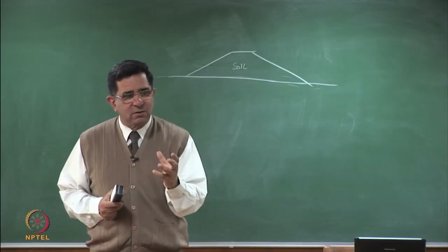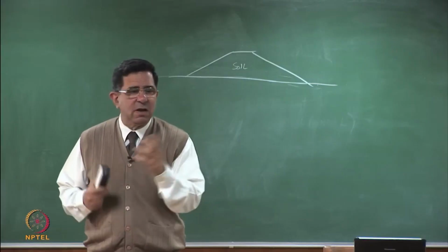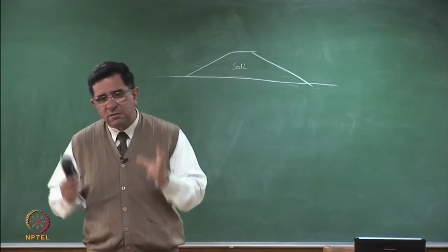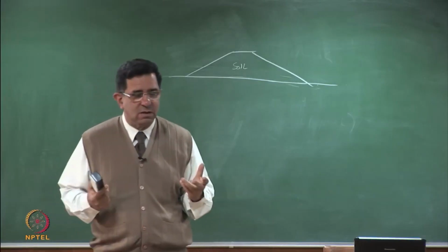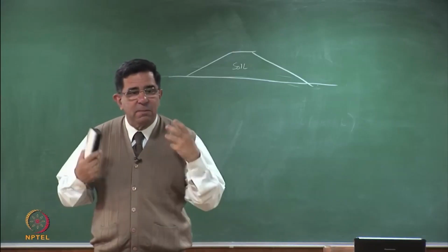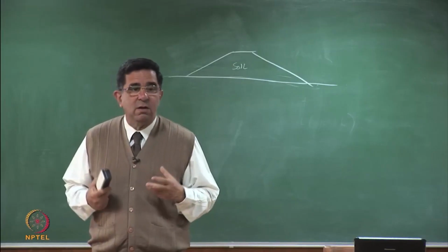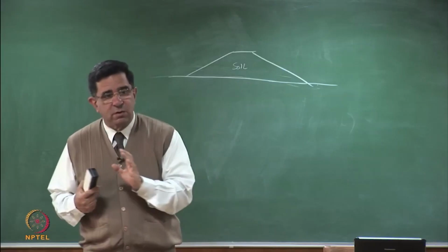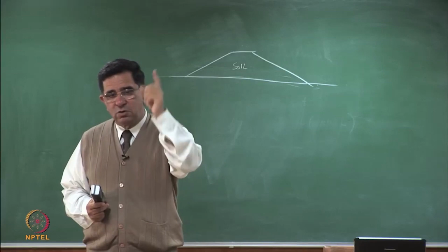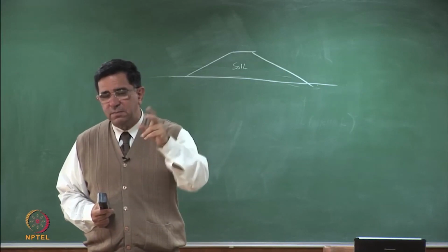It's like if you have 10% gravel in sand, will it make a lot of difference to the angle of shearing resistance of sand? If the particles float amongst the sand particles, they are not coming in touch with each other. So only when the portion of gravel becomes significant, 25% or more, do you start to have an effect of the coarser material. So sometimes you can even remove the coarser material so that you are able to do the test within the limit. So use a large direct shear box, do a slow test so you get drained parameters.